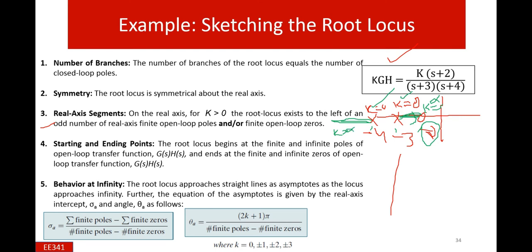So there are two root locus lines. One starts from the -3 pole and ends at -2, and the other starts from the -4 position of the open loop pole and goes to infinity. There is no need to find the centroid here, and this concept will be understood in the next lecture.